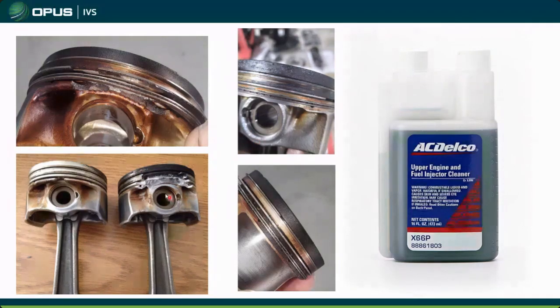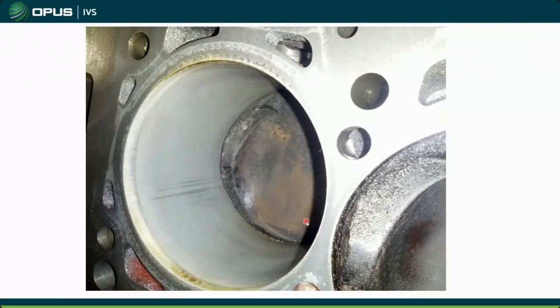Some of the other problems with these 3-liter pistons, I'll show you here in the next slide, is carbon scoring. This is actually one that I did. I mean, you can see how bad this carbon really gets on here and on the piston, on the face of it, and you can see this scoring. Now, this scoring, you can't really get a nail in it or anything, but this is actually an iron sleeve that's pressed into the block, and so it's very, very thin. I think just about a millimeter thick. I mean, there's not much to it.